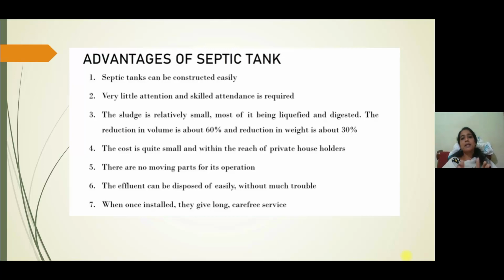As you all know, the septic tank can be constructed very easily and very little attention and skilled attendance is required for the operation of this septic tank. And the sludge is relatively small and most of it being liquefied and digested. The reduction in volume is about 60% and the reduction in weight is about 30%. So the removal frequency, that is the cleaning frequency, can be from 1 to 3 years.